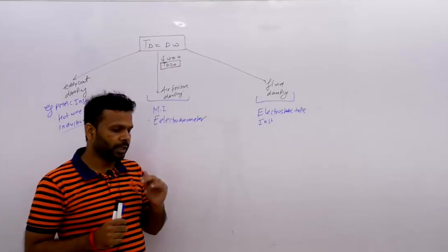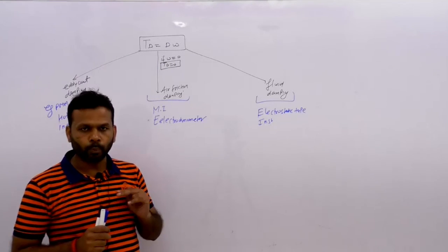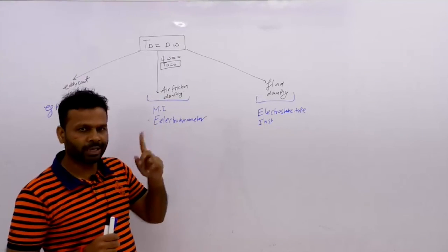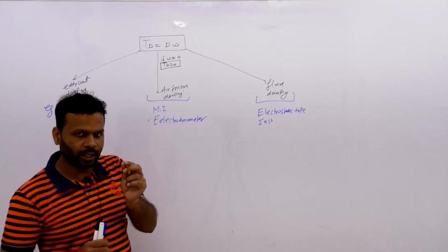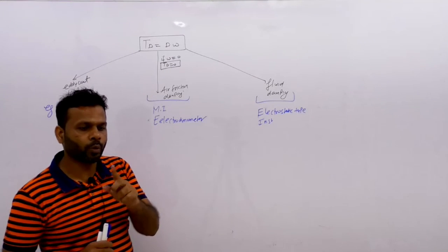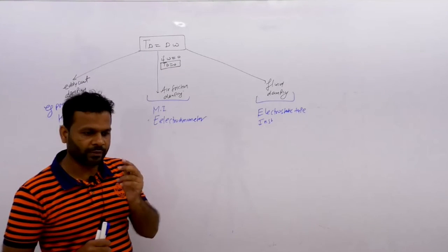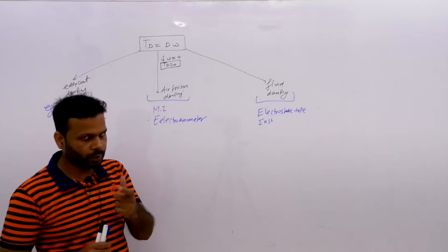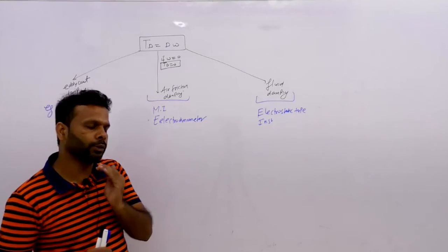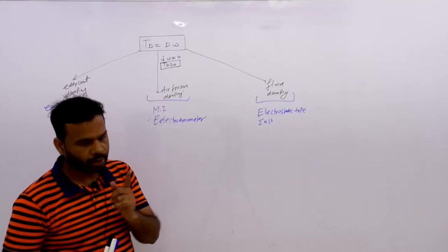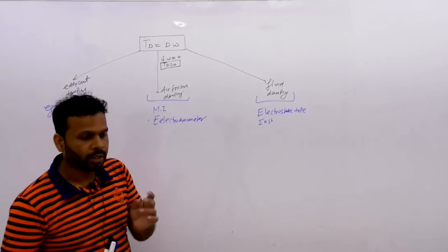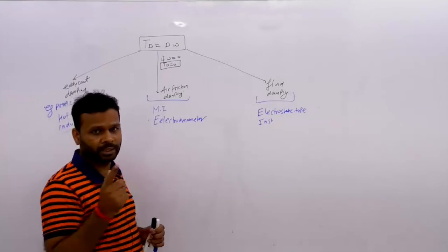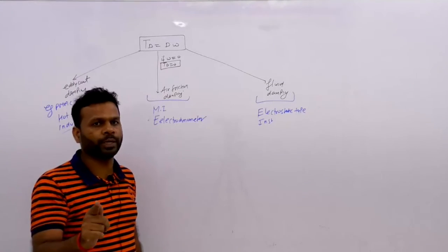Let's start again. When the moving coil is moving in the field provided by your permanent magnet, this magnetic field is cut by the moving coil core. Now the core has an undesirable property, the electrical property. Then according to Faraday's law, an EMF is induced in your cylindrical core. Now your core is closed, so there will be circulating currents. These circulating currents are known